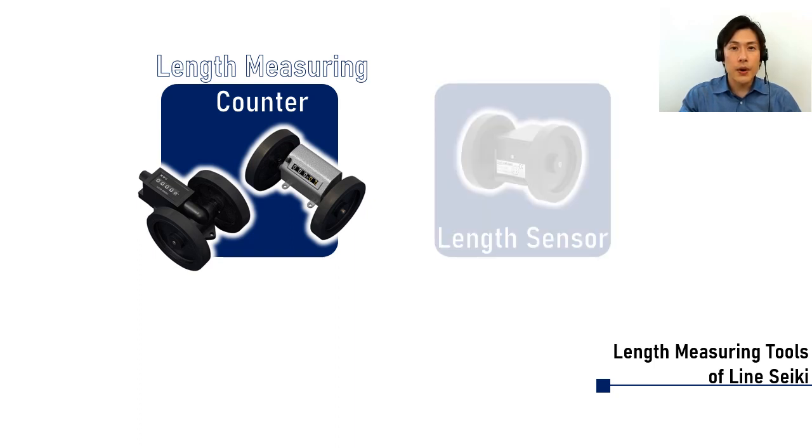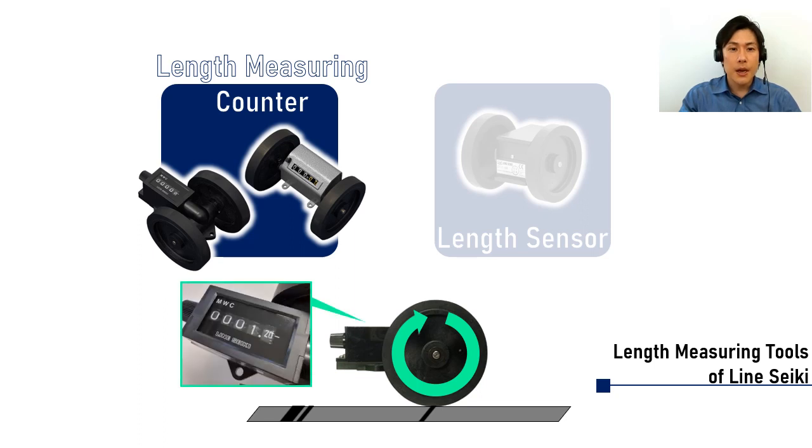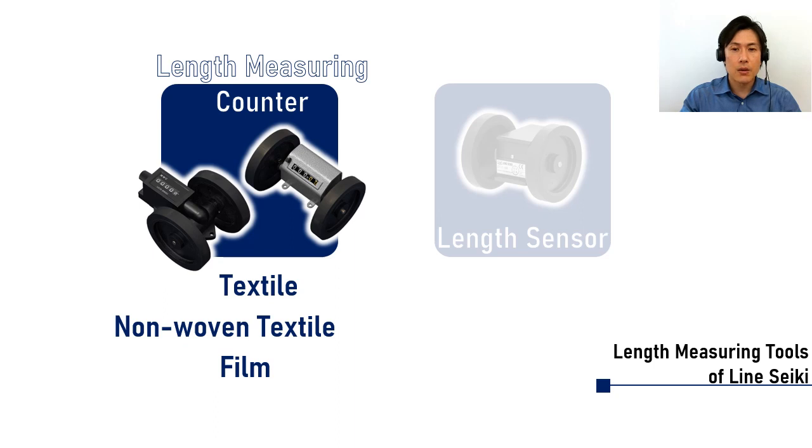A length measuring counter has two wheels and they rotate on a measuring object. You put the counter on the object, such as cloth or plastic film, like this. When the object moves, that motion makes the wheels rotate like this. As a result, the length of an object can be measured. A lot of length measuring counters are used in the industries of textile, non-woven textile, or film manufacturing factories, and so on.